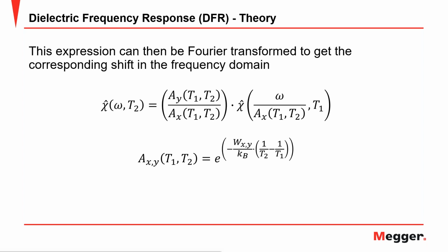And that condition is not going to change. What is critical here again, if you want to go from 30 degrees C to 20 degrees C, I have seen the majority of the mistakes in the field is measuring that temperature. Because sometimes the temperature gauges are not accurate, because sometimes the transformer has not been immersed in oil, because they drain the oil for, say, a dry-out process. So be careful about the temperature. The better you provide the temperature to the system, the more accurate the assessment the system will give you.